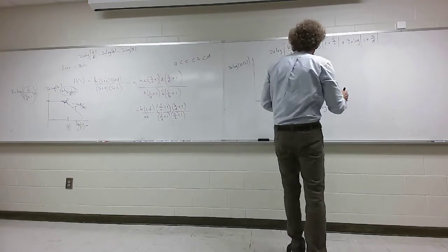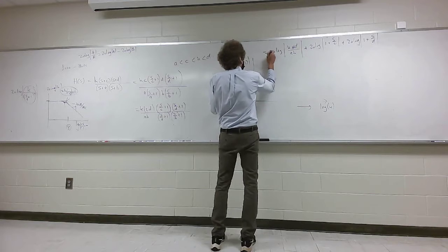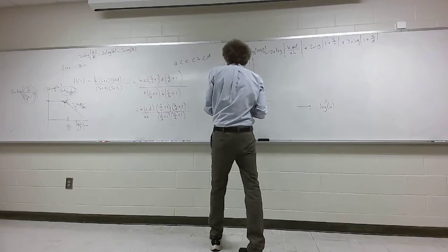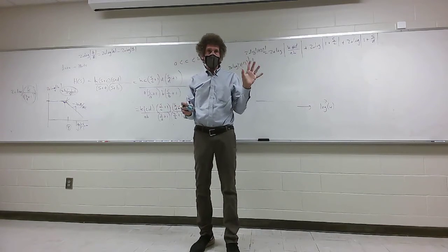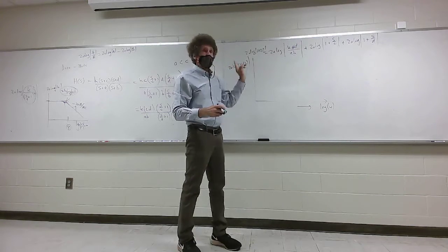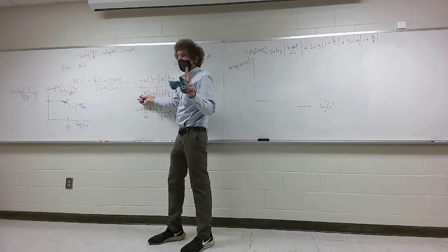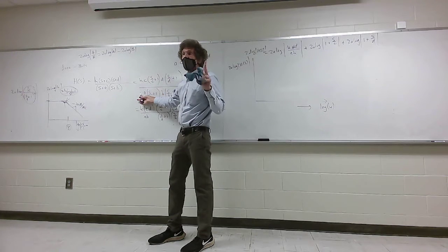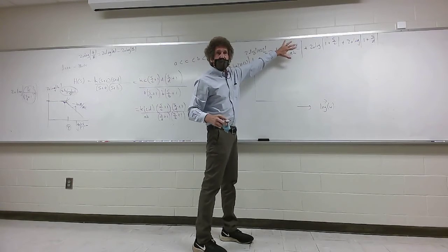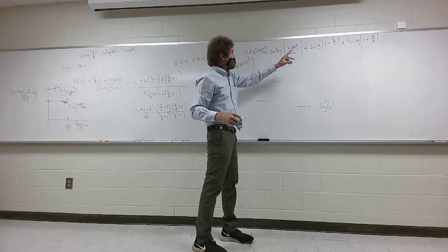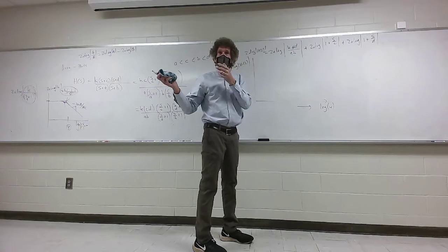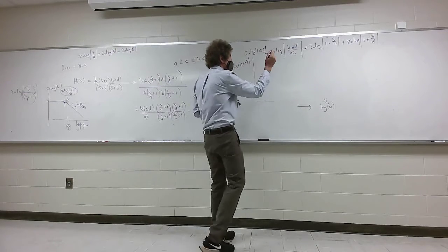All right. Now, here is what that 20 times the log of my fictitious H of S looks like. And here's how you do a plot like that. Now, sometimes you can't, but I'll get into it. That's if you have just a 1 over S term. If this had a 1 over S term, then you can't do what I'm about to show. But the way you normally do this is you start with the constant and you evaluate this constant. The 20 log of K, C, D over A, B. That's a value, it'll always be there. Y'all follow me? That's what it is when you're less than A.